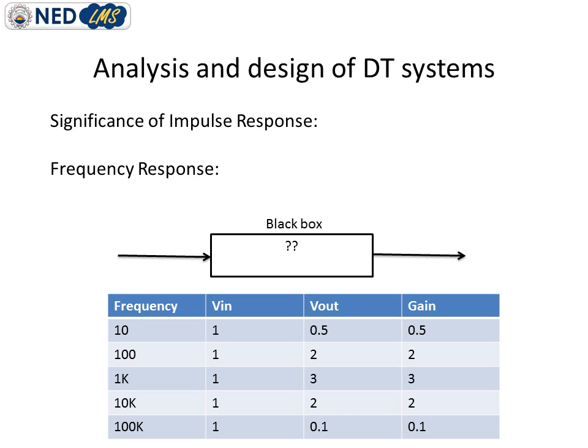And suppose this system gives me an output voltage of 2 volts. With the help of this available information, I can again calculate the gain of this system, which appears to be 2, as 2 divided by 1 is 2. So at 100 Hz, I came to know that the gain of the system is 2.